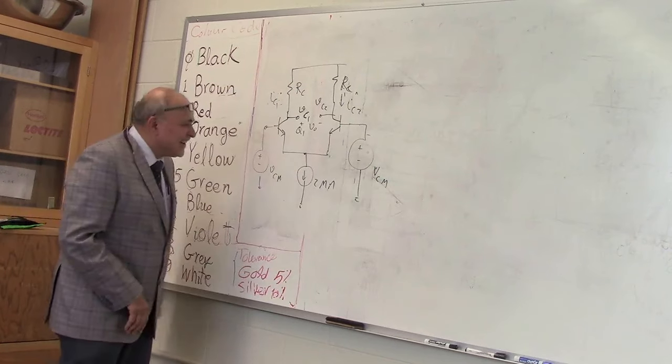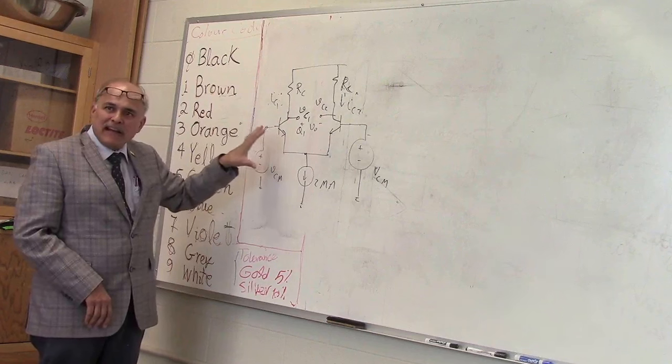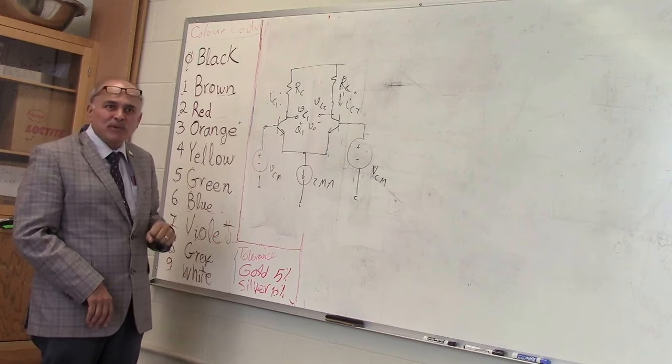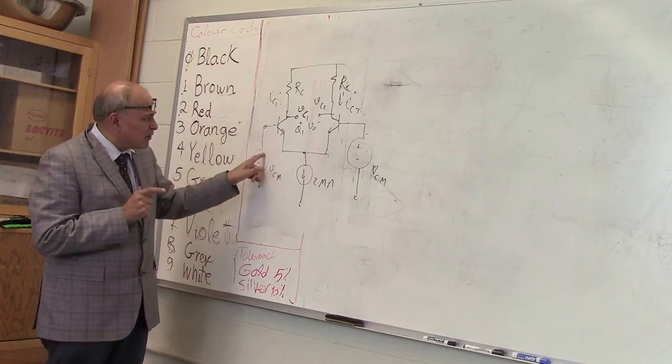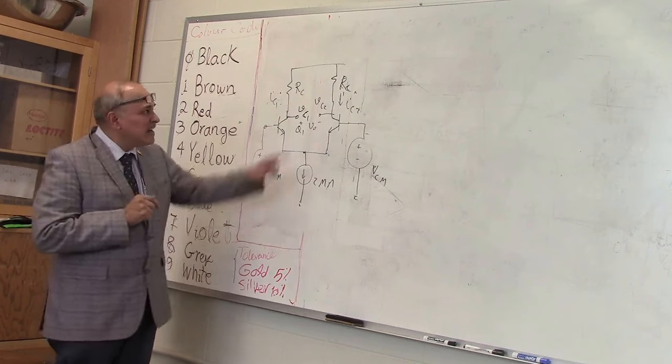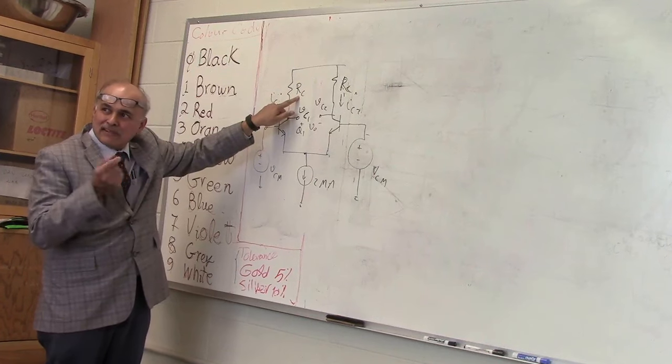Okay. Alright, so this is 2 milliamps. So ideally this will not amplify any common mode signal. The only time it will amplify a common mode signal, common mode means the same voltage applied to both, is if these RCs are different. Okay, if they are slightly different.